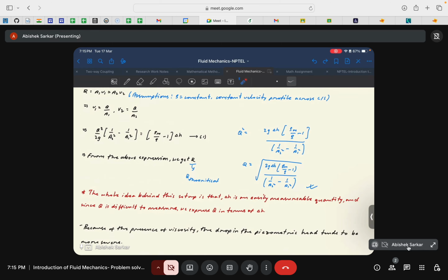That is again a time consuming task, and for better working you may want the instantaneous value of flow rate through your pipes, right? That's why people use a venturimeter, or sometimes an orifice meter, to find the volume flow rates. Again, to remember, the principal utility of a venturimeter is to find the volume flow rate through a pipe, not the velocity. Of course, one way or another velocity can be obtained, but that's not the primary task for us. The primary utility of the venturimeter is to find the volume flow rate.